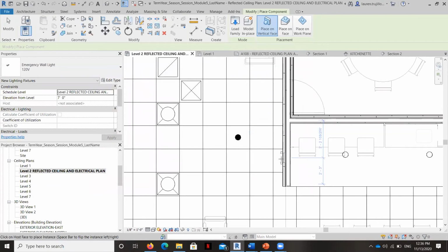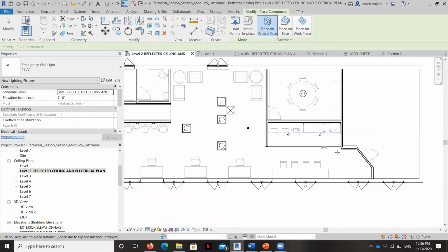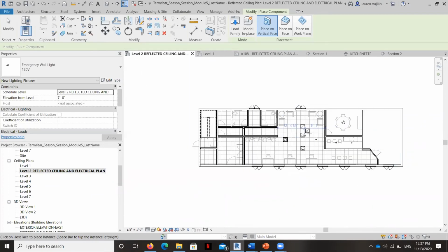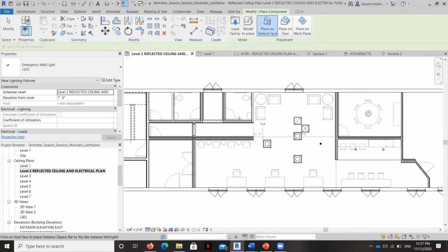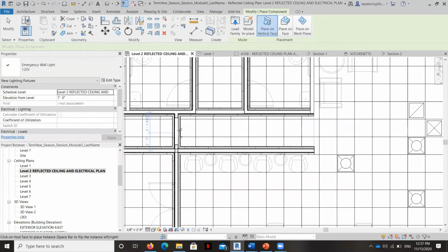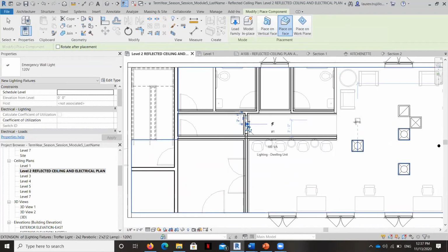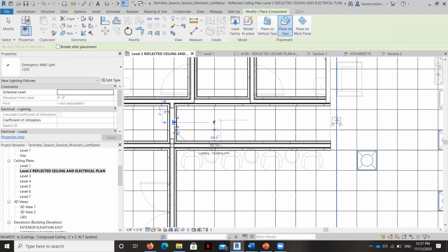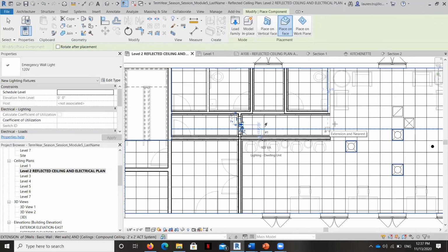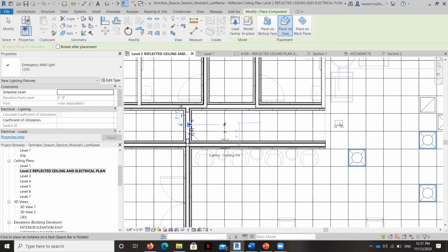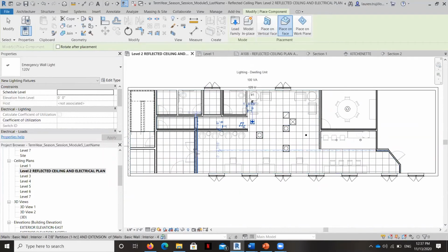Now this is wall hosted, right? Because it goes above an exit door or indicates an exit door. So we would have to put it right here. This is going to be 1. And then we would actually also have to mount it to the ceiling here as well, so that people could see that there's an exit door located here. So I'm going to just put it right there for now. And then we'll put another one here.